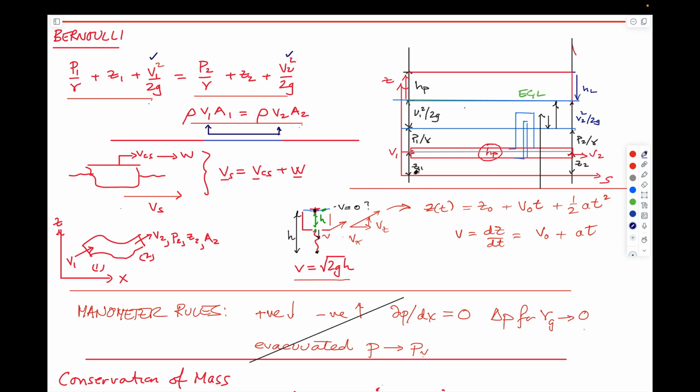We explain Bernoulli behavior in terms of, say, flow in a pipe. The elevation, pressure, and velocity heads represent the individual heights on this. For Bernoulli, where there are no head losses in the system, the energy grade line is horizontal and has to be the sum of elevation, pressure, and velocity heads upstream and the same downstream.